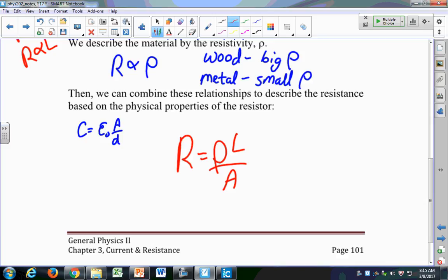That's probably the hardest thing, because it doesn't always make sense to us that if I have a wire that's this small, it has a certain resistance to the flow of electricity, but if I make that wire this big, then the resistance is decreased quite a lot. I think it doesn't make sense to us because we think, oh, there's more material for it to go through. But really you want to think of it as, oh, there are more conduction electrons to carry the electrical energy in that bigger piece of metal. That's why a big pipe has little resistance. A small pipe has a lot of resistance.